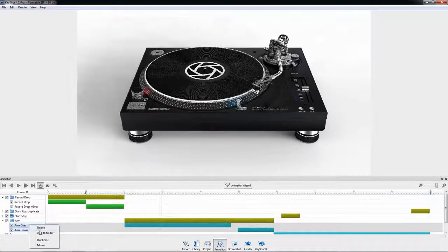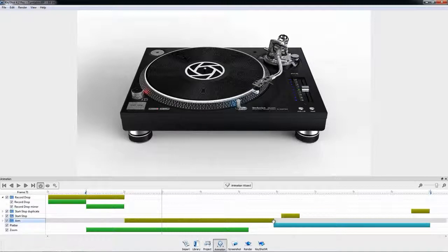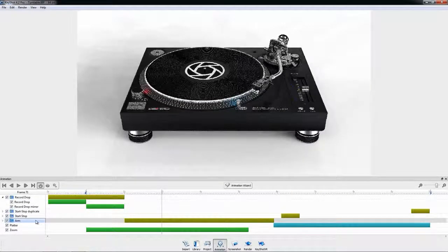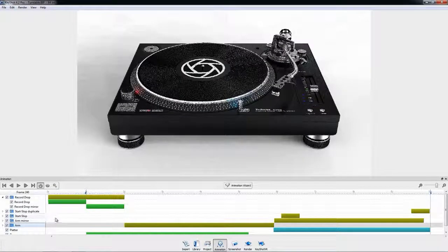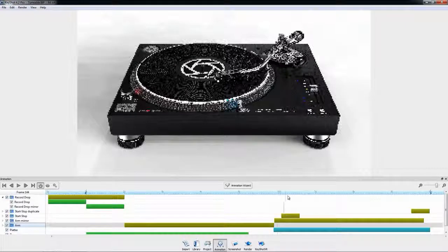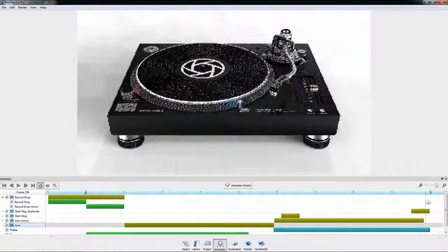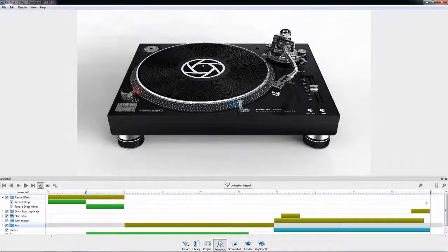Or right-click on the animation name and add nodes to a folder and adjust all the contents in that folder. Here in the right-click menu, you can also duplicate or mirror an animation or folder. If you intend for the final animation to continuously loop, the mirror function will be a valuable tool to bring your camera back to its original location, or bring your exploded view of parts back together.